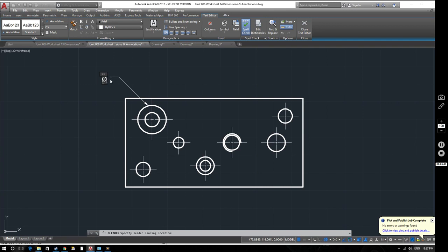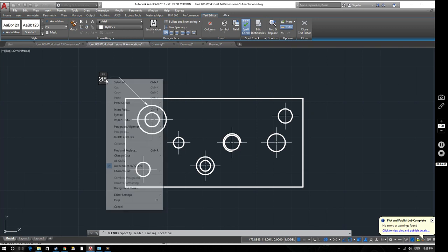So this hole is 8mm in diameter. But as well as being an 8 diameter hole through this block of metal, we're also interested in what's this here. Well, this is a countersunk hole, and therefore we want to show that this is a countersink and not a counterbore. So what we're going to do is insert here now the countersink symbol.